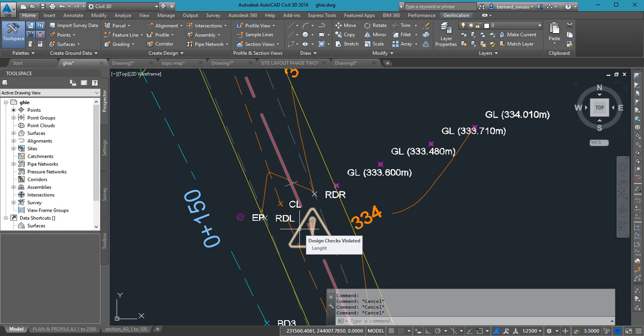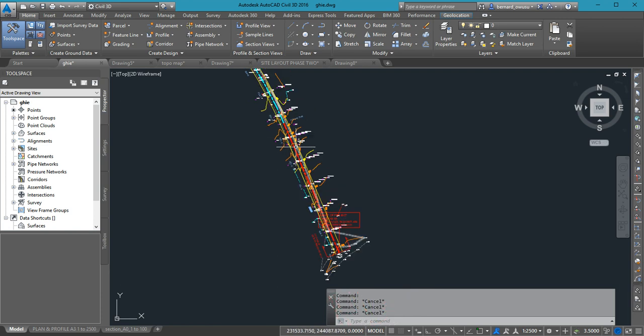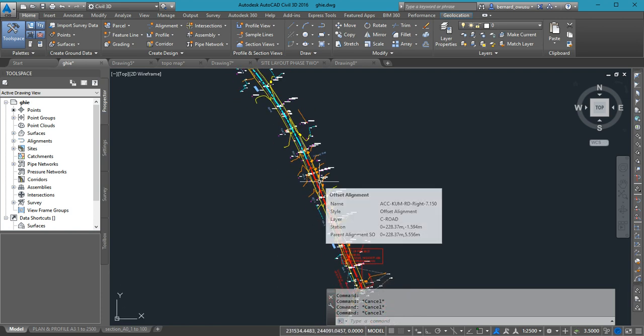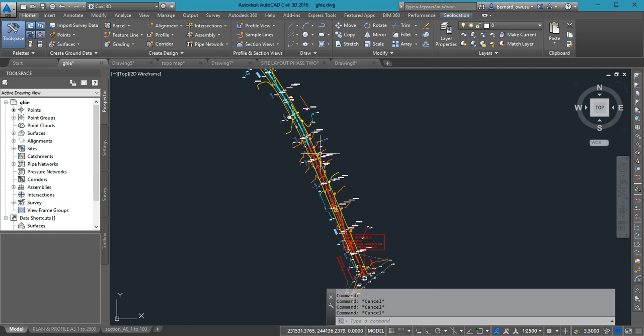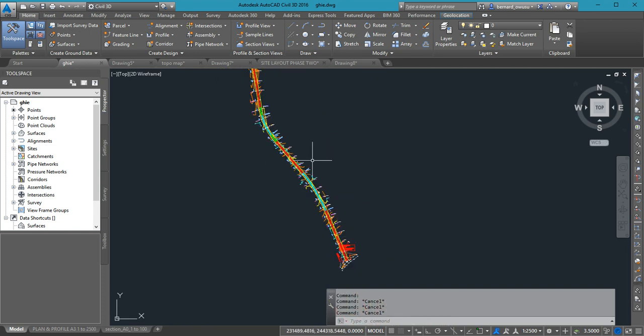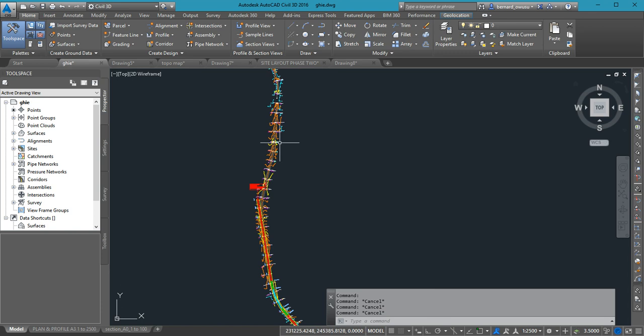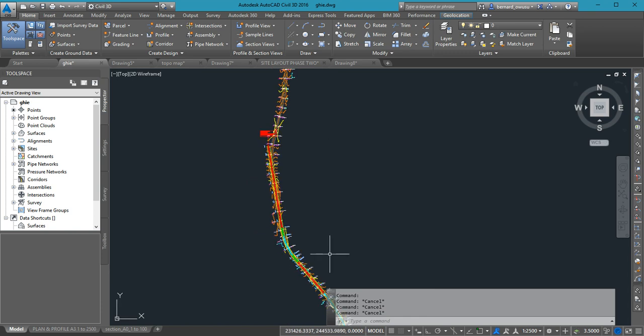This means that the length I've inserted there is for length. It means that the length is shorter than what is expected to be. Now, for the tangent, in doing design, there's something called a broken back curve. And this particular warning was done specifically for broken back curve. So if you have a tangent between two curves in the same direction, for example, if you look somewhere here, the next curve that I'm going to put will also be a right-hand curve. So this is a right-hand curve. This is also a right-hand curve. So this is a broken back curve. We call this a broken back curve.